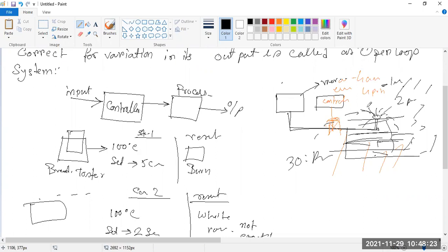It has become highly dry, and the temperature is high, but the system will start only on timing, because no controller is acting, only on and off. There is no feedback from your field or your soil, whatever the moisture is, whatever the humidity is. Okay, so this is an open loop control.